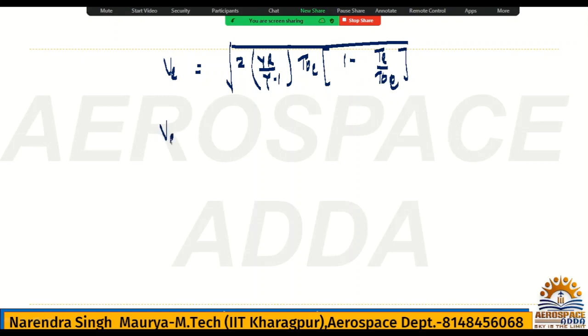Then what you can write, VE equals 2 gamma upon gamma minus 1. This R is the characteristic gas constant. We will write universal gas constant Ru divided by molecular mass of the propellant, into T naught E, which is nothing but the total temperature in the combustion chamber.